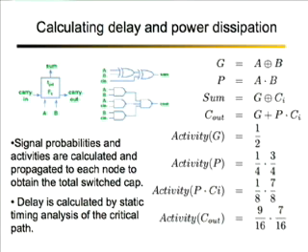And in order to calculate the activity at each node of the circuit, we have done a probability propagation, which is again a standard way of figuring out what is the total switched cap of a big circuit. So I want to point out that when we provide results for switching energy, switching power, as well as average power and average leakage, it is a good estimate because we have incorporated the probability of switching and activity at each node.